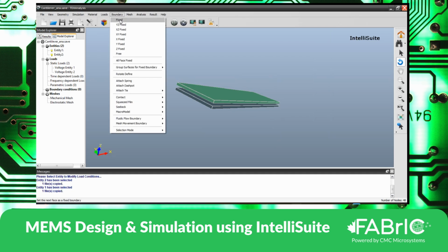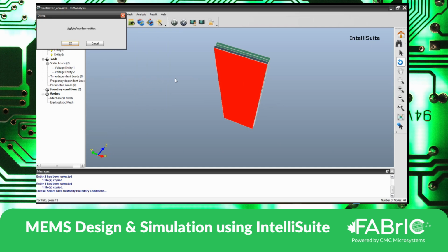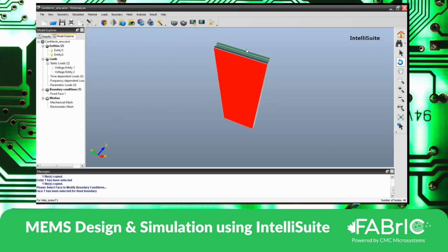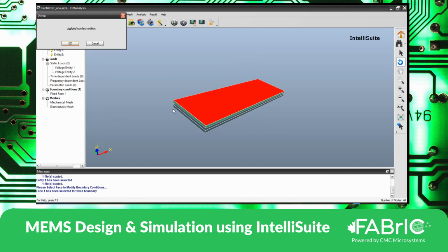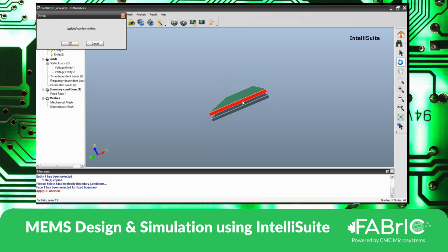Now boundary fixed. I need to fix a boundary condition. I would say select the bottommost, and don't try to click on the geometry to rotate the structure, because the face will get selected, which could be misleading for you. So use the outside area, hold the left button of the mouse and rotate the mouse, and the geometry gets rotated. I select.